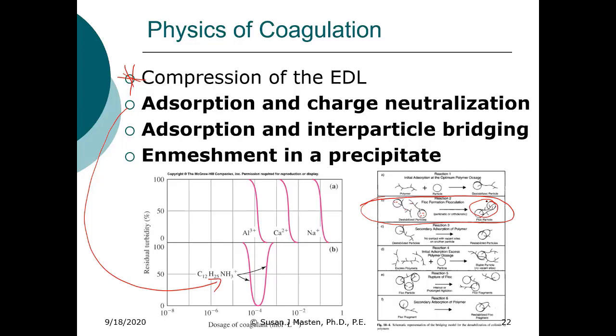Now, the challenge with this is that the doses of these organic polymers are very, very sensitive, or coagulation is very sensitive to the dosage. If you're not careful, you can see here we've got this particle, and the long chain bends, interacts with the particle, and you're not getting any interaction with another particle, and you simply restabilize the particle.